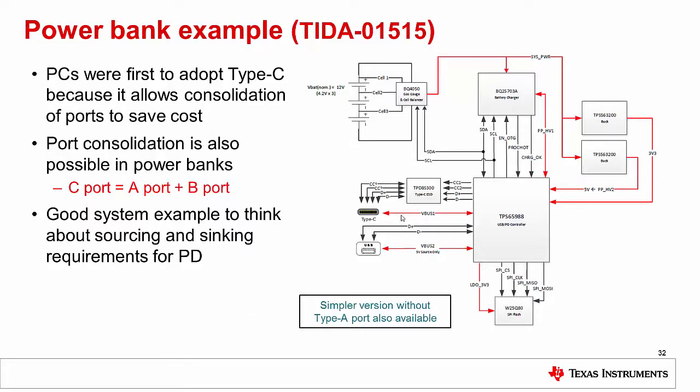So the system that I'm going to talk about is based on a reference design that TI has done, and it actually has a Type-C port and a Type-A port. Of course, the Type-A port is optional, but there's still a lot of legacy devices out there that may want to use A to B charging. So I won't discuss that much, but it's there on the design. This reference design leverages the BQ25703A battery charger and a USB PD controller from TI.